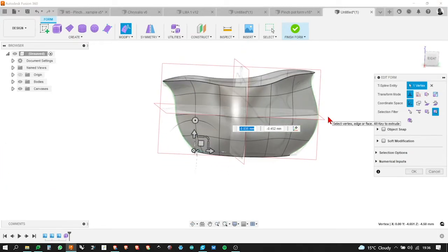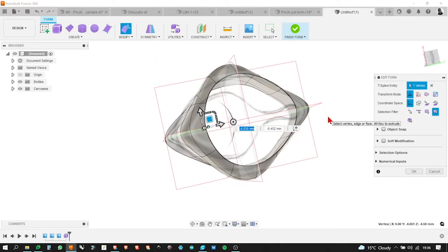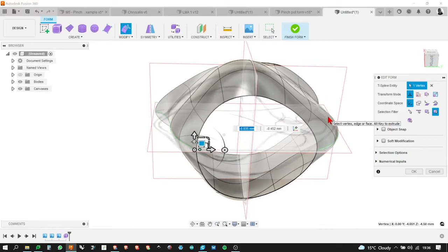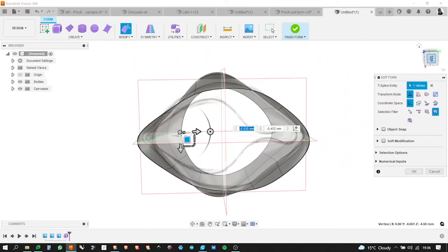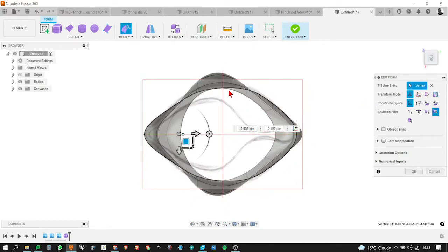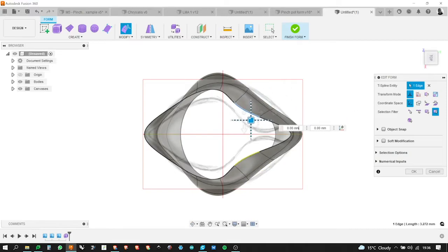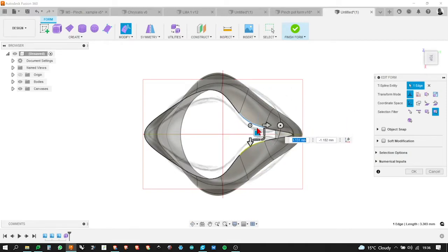If we wanted it to be a circle, we couldn't ask it to be one. No, I don't think so. I mean, there may be ways of doing it and snapping it to a constraint. I haven't found them. It's much more for modeling more freely, but there may be ways of doing it. I have to say, I'm not a complete expert in the sculpt environment. Could you draw a circle in a sketch, maybe, and then reach faces to it? Yeah, you could do something like that, absolutely, yes.